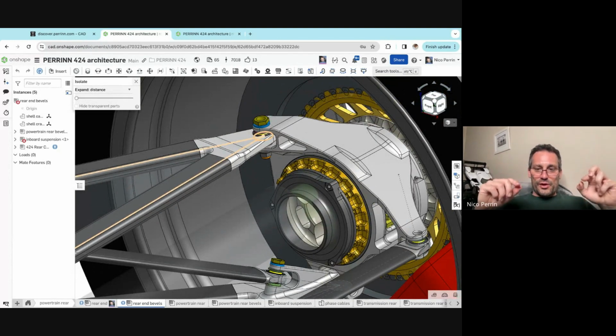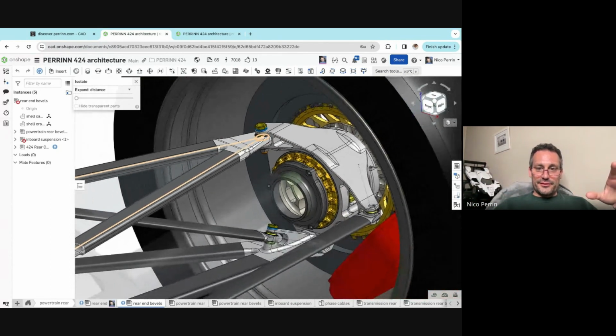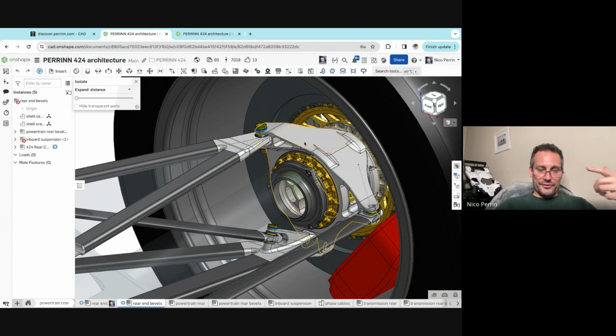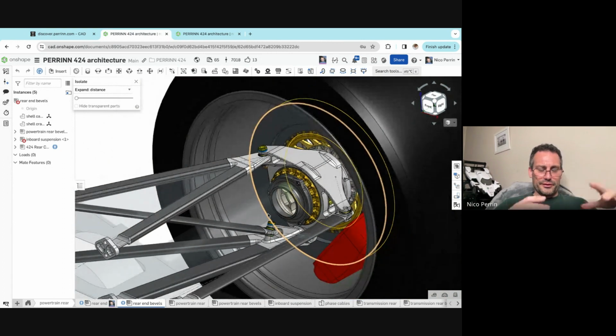the exercise here was lightweighting. I said to Isla, look, the features need to be this, that. I looked at the kinematics, and then he went through different iterations of how to design the upright, given the bearings that we have and the axle that we had designed for the LMP1 some years ago, and just trying to make the assembly lighter and lighter. And we actually went a long way, and we gained something like 2 kilograms on the assembly over a period of 6 months of working together on this.